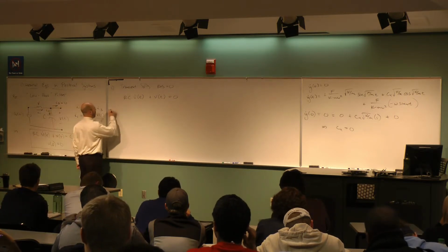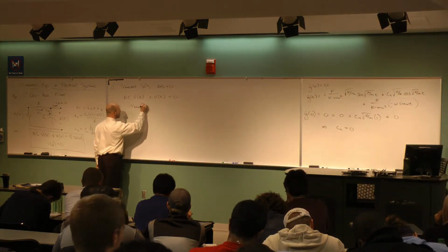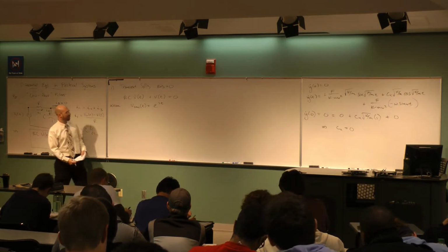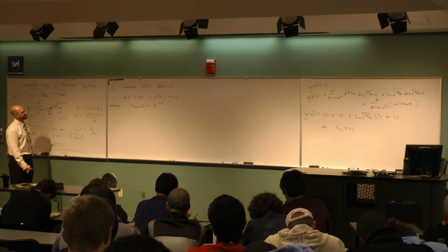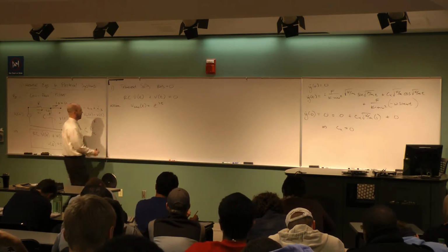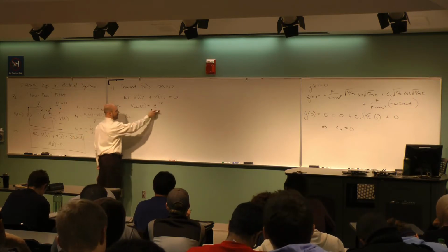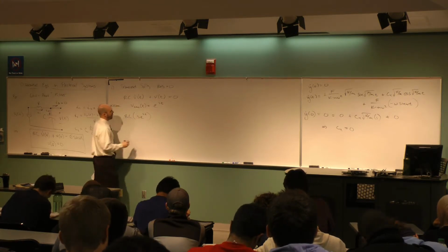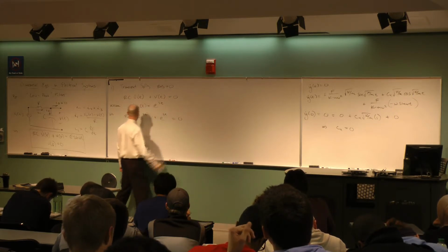What we're going to assume is e to the st, so V transient of t is equal to e to the st. The reason we assume that is so that when I take a derivative and add it to itself, I'll have an e to the st in each term, and I can add up like terms and get 0. Let's plug it in. RC, the derivative of e to the st is S e to the st, plus I've got V of t, which is e to the st, and that equals 0.